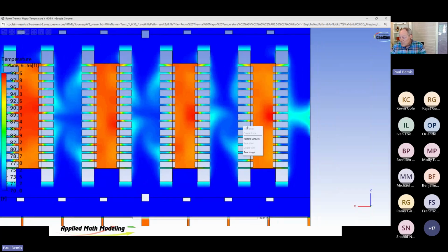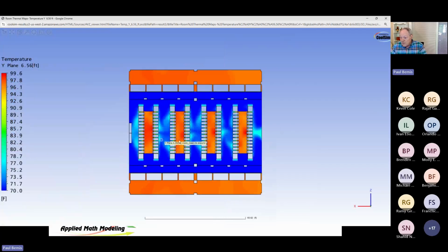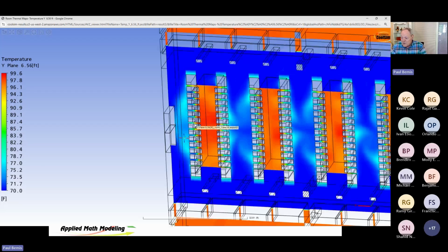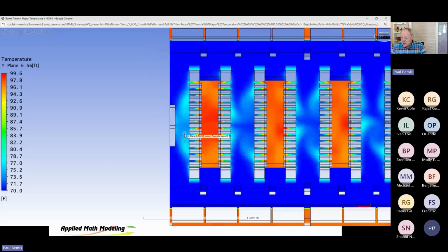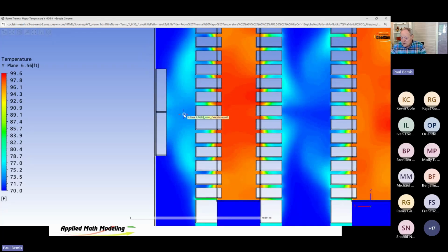Over here, we're problematic. This is where the air handlers are off. Over here, I believe, no, they're off on this end. But you see the PDUs are contributing to some problems here. The PDUs are dumping into the room. They're not ducted to the ceiling. So the power distribution units are dumping heat into the room as well. You can see it there.